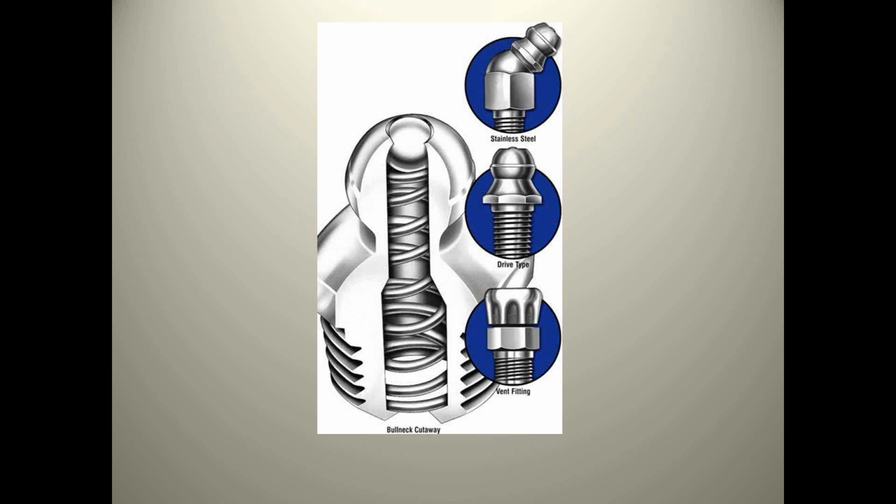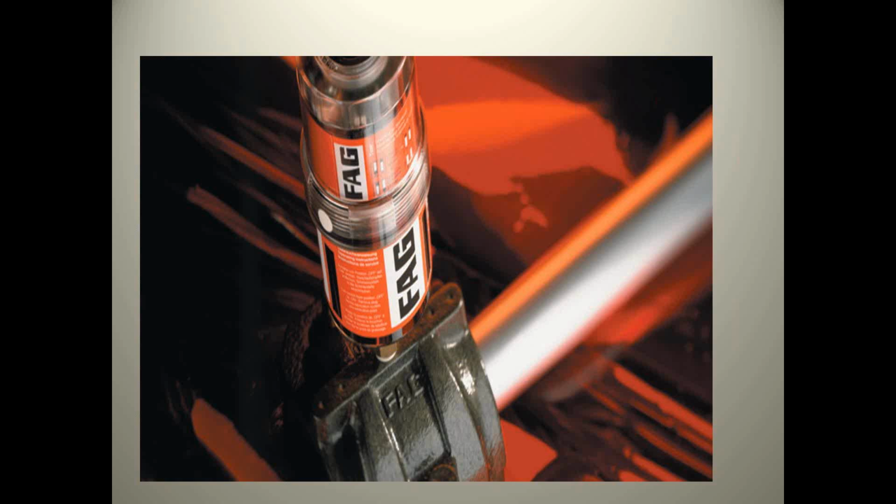Now, some things we can do to get away from that in lubing is take these off and install automatic lubers. One of the things they do, like this one here, is keep that failure mode of a dirty grease gun or somebody pumping particles in every week. Now we stick this automatic luber on there one time, so no particles can get in, there's no dirty grease gun, there's no dirty grease nipples, and it puts clean synthetic grease into this bearing all the time.